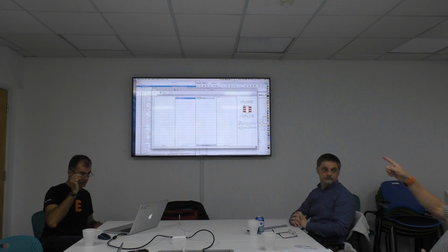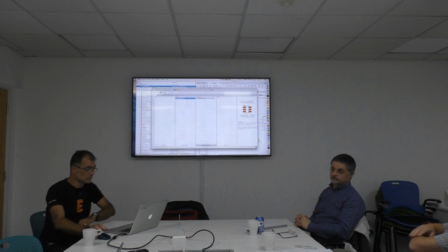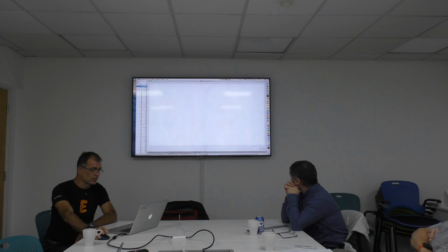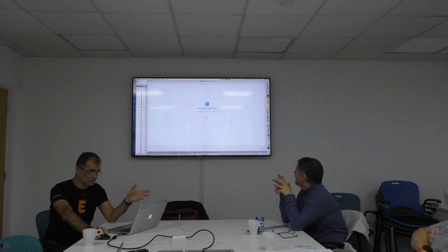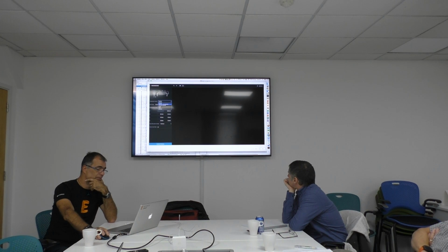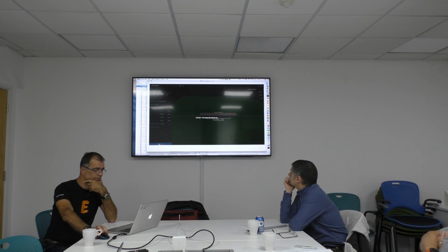But that did resistors and passives as well, by the looks of it. Yeah, we can also try a resistor. The package creator. So I simply will use random values. I go Excel. I can define what is it, resistor, capacitor, polarized capacitor, a diode. If you use a capacitor, polarized for example, then it's a pad shape round, what is B, that's the diameter of the wire here, then some sizes, I simply say update preview.